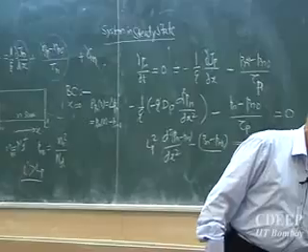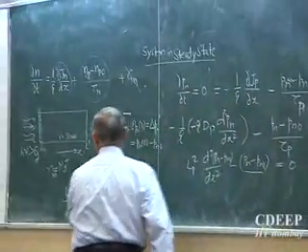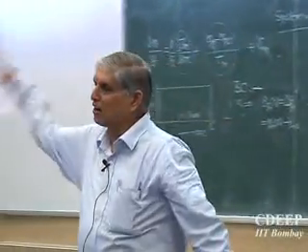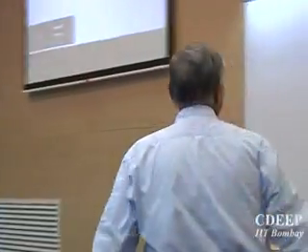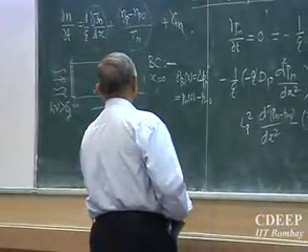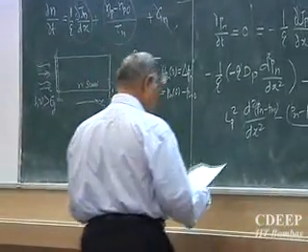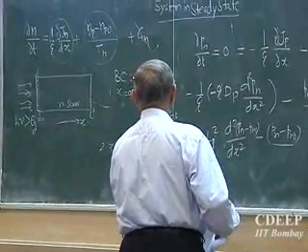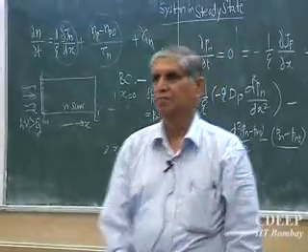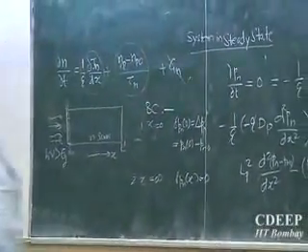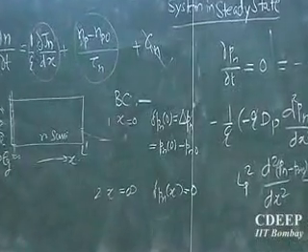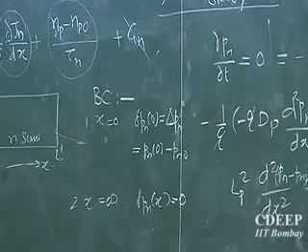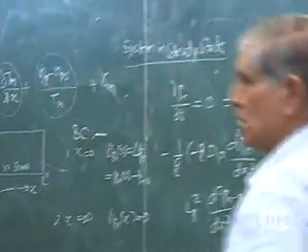What should be the second boundary condition? On the other side, L dash, as I said, is much longer than the diffusion length. So at x equal to infinity, delta Pn(x) is how much? 0. Far away from this, the concentration should be Pno, which means delta Pn(x) should be 0. So two boundary conditions, simple differential equation.